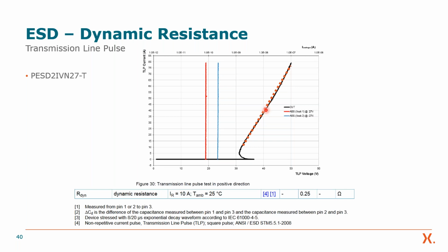If you want to understand if a device is working well together with an internal protection, you should also consider that the internal protection should have a measurement curve on the right side, so that in the case of an ESD event, the external protection is activated before the internal does. Otherwise, it's not helping. This is the general idea.